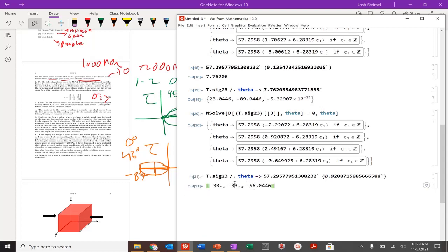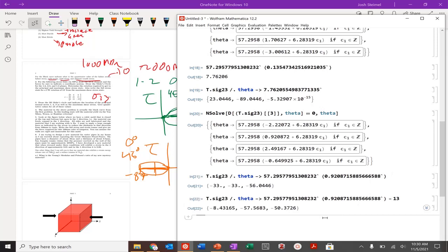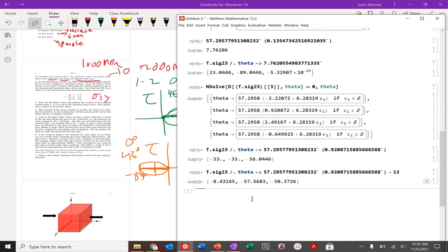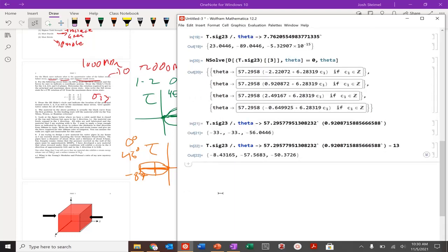And center, center, and then this is my radius, my maximum shear. Fantastic. And again, if I want the stress state 13 degrees clockwise from this maximum stress state, I do minus 13 because it has a clockwise rotation. So I'm looking at that rotation to get to maximum shear, and I can just do minus, and there it is. There's your answer.